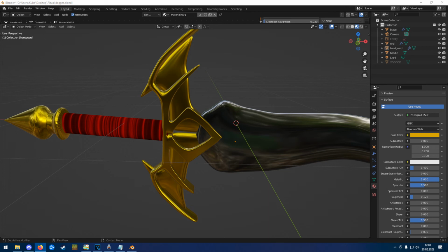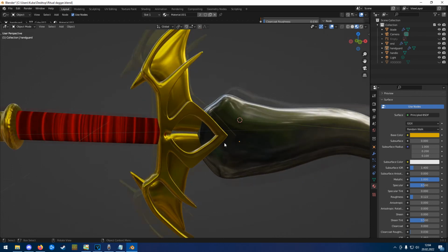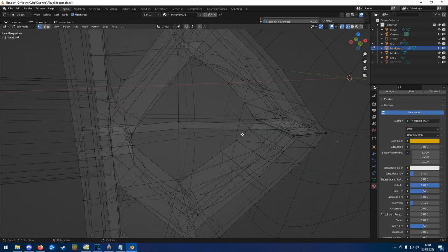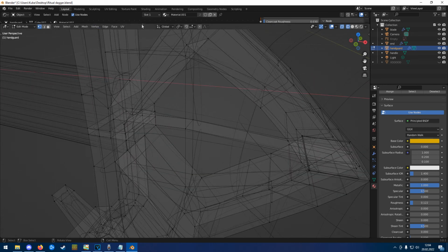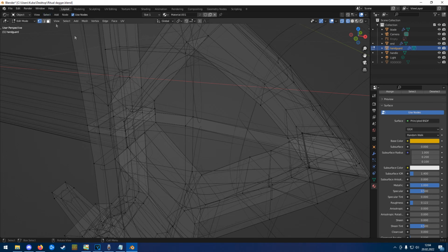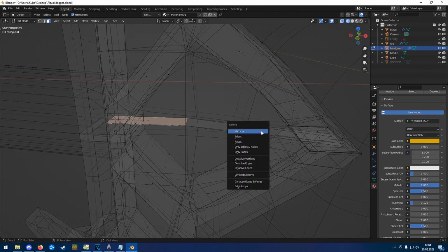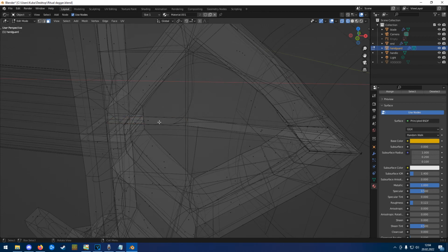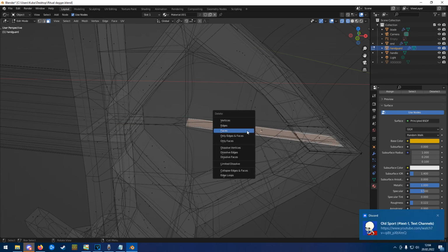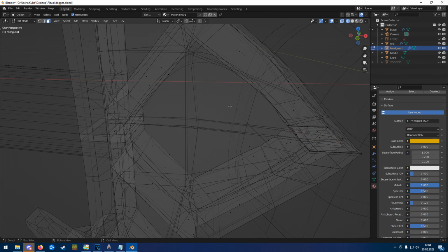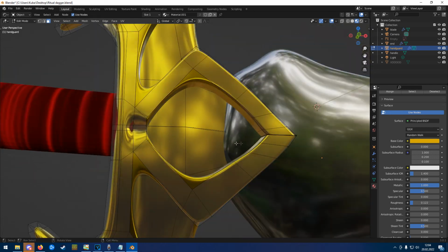First off though, we do a little fixing, just because I wanna show you how simple it is. The center of the handguard looks horrible. All you gotta do is go into edit mode, wireframe, wall selection, and remove these 4 walls. Now look at how smooth it is.